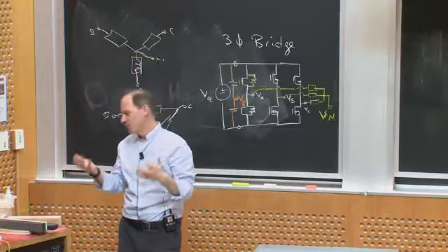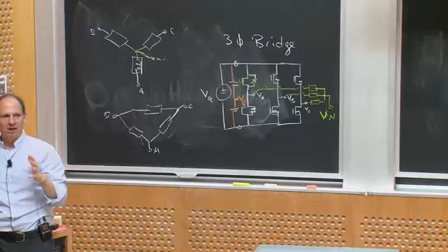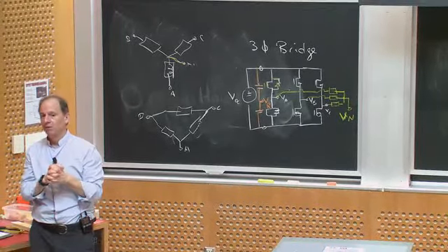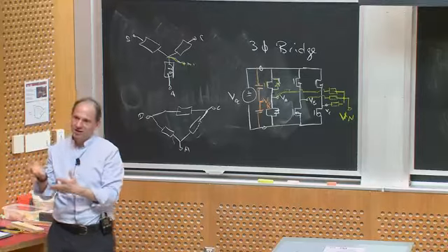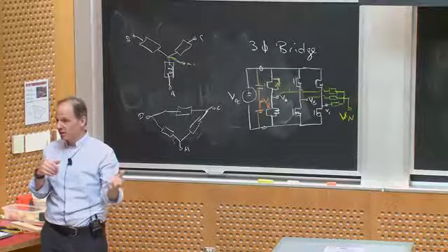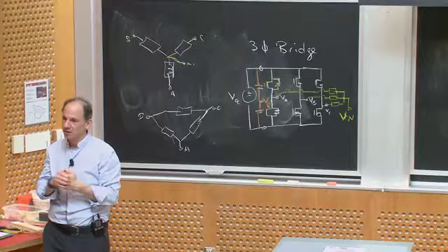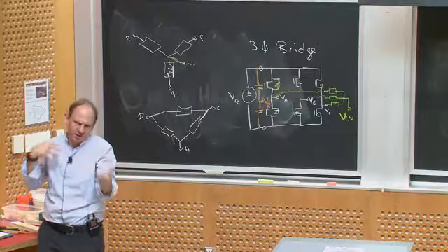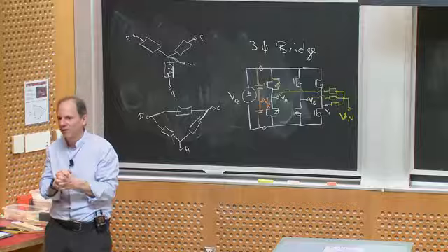And so, maybe until 5 years ago, or maybe 10, it was most common to use IGBTs, especially at high voltage. More recently, with wide bandgap devices, people are starting to move over to sometimes IGBTs, but mainly FET kind of structures, because you can get away with that, and it turns out to be lower loss. So whichever switch gives you less loss is ultimately what you want to choose to use.